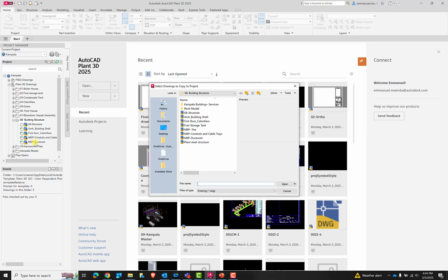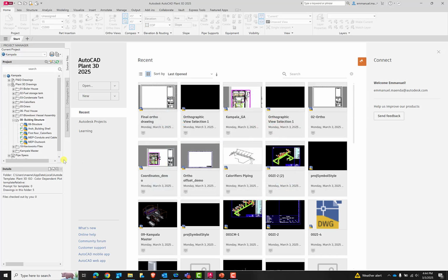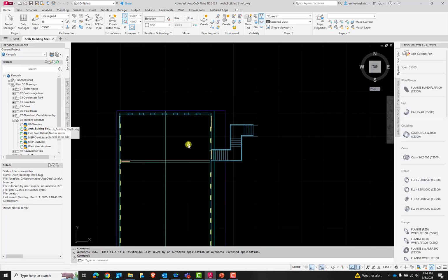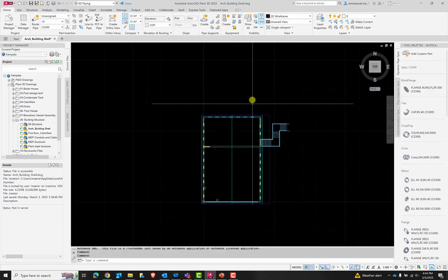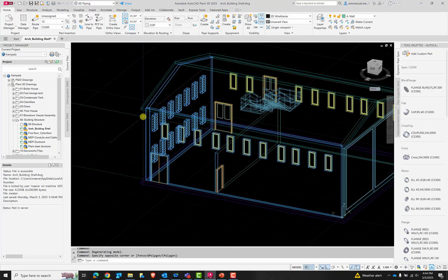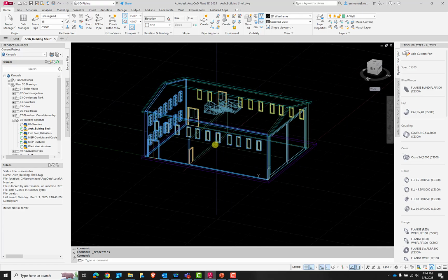The other thing that I also want to show you is that you can also add your Advanced Steel model. This is just an example of a very basic, super basic AutoCAD Autodesk Advanced Steel model that has been added. Then the next step, once you have that in, is that once you open them, you can actually see these models, and even when you click on the object itself and want to extract the properties, you can see the layer properties are also visible, as you can see from the example.